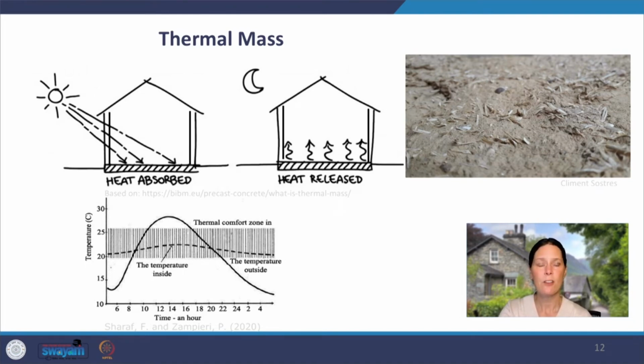The thick envelope of brick has the ability to retain the sun's heat for a long period of time, before emitting it at night as it permeates into the interior space as the night temperatures drop. The brick then retains the night's cool temperatures for daytime disbursement. The bricks function as heat regulators that are slow to heat up and slow to cool down. The variable is the thickness of the brick to provide the correct lag time.